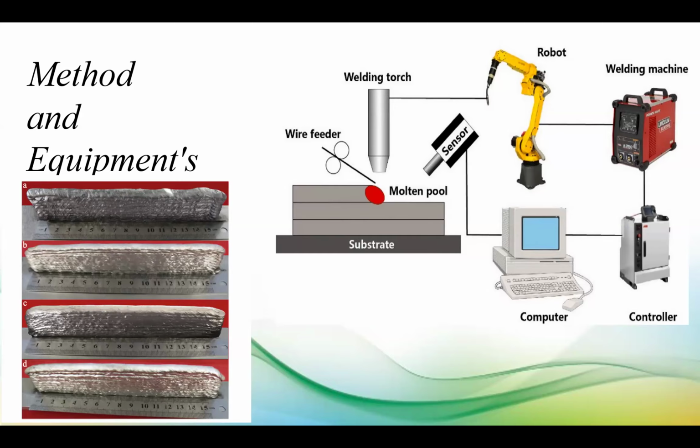It will be very difficult to do wire arc additive manufacturing by manual methods. Theoretically, we can do the welding process and the metal deposition, but practically it may not be possible. Only using a robotic system or a dedicated CNC system can we do this process. And the welding machine and the robot must be connected through a compatible controlling system.